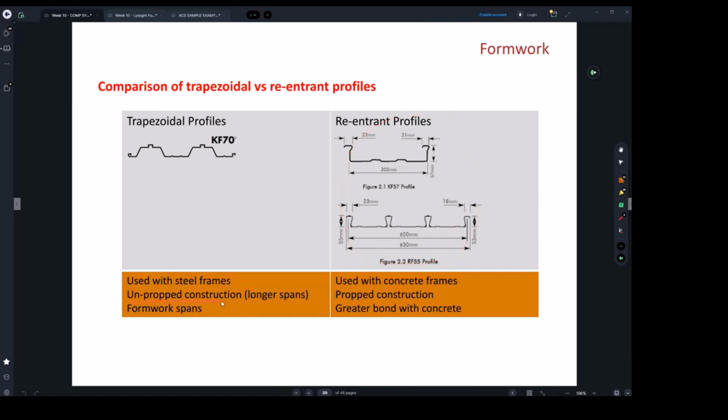But as I said, for bridges or heavy duty constructions, usually you've got very tall floors. In some of the towers they build, usually the first floor goes up to 9 meters in height. It's too expensive to prop for 9 meters. So your concrete slab is actually 9 meters higher than the ground.